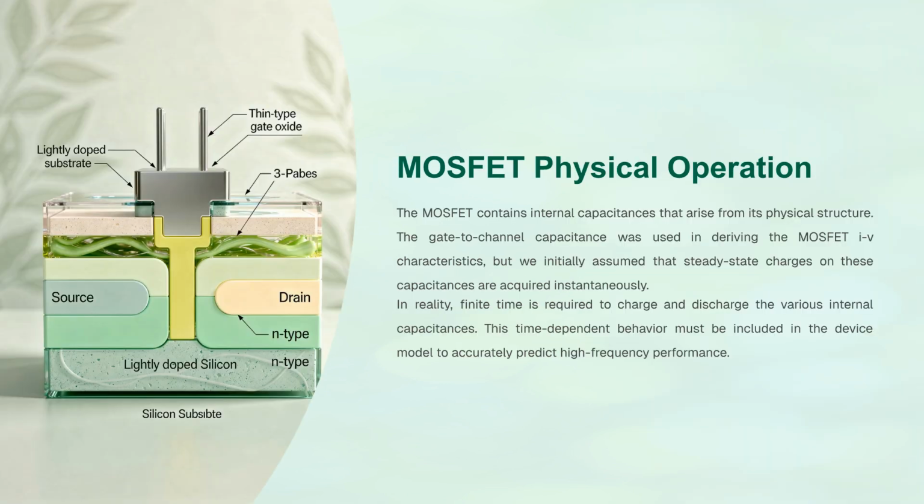The MOSFET's physical structure gives rise to internal capacitances. While we initially assumed instantaneous charge acquisition, a finite time is required to charge and discharge these capacitances. This time-dependent behavior is critical for accurate high-frequency performance prediction.